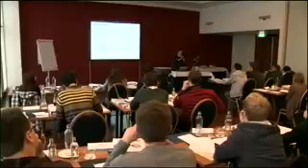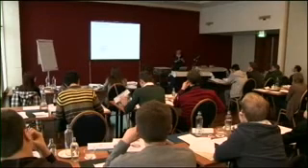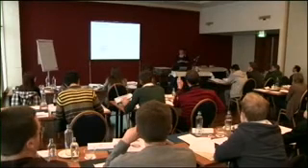What we can do, though, which is another technique we use quite a lot, is if you crush your concrete, then you can basically try to pick out the big bits of aggregate. And then you can be quite effective in getting a material where you enrich the paste phase and you minimize the aggregate phase. Okay? Any other questions? Yeah?